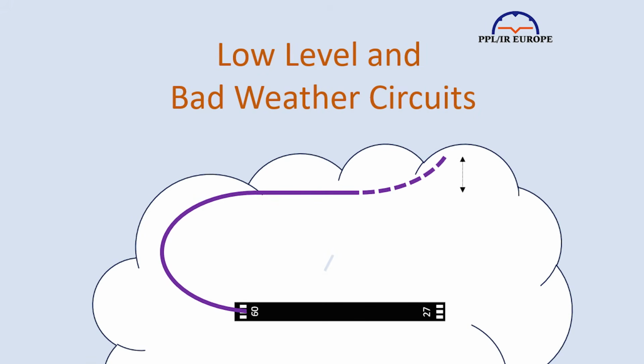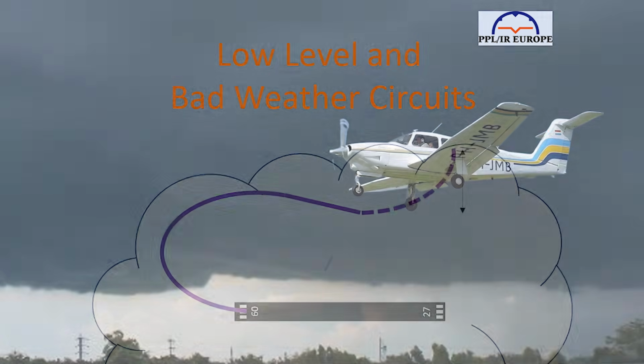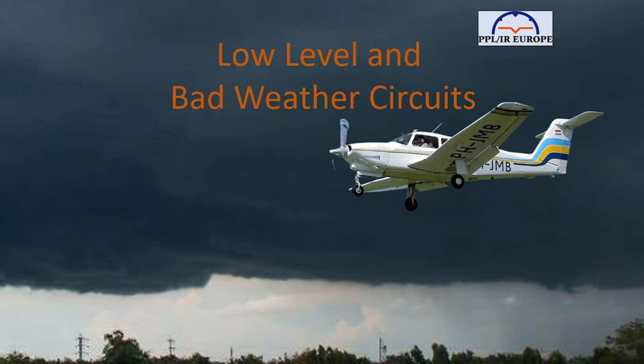From a 45-degree angle, that's manageable, about 250 metres closer in, but from a 90-degree cut, using a rate 1 turn, which is the maximum I'd suggest given your low height and the dangers of disorientation and spinning, it's close to half a mile. I would suggest being fully configured for landing before you join downwind, at least as far as is sensible and permitted in your aircraft type. This saves configuration changes and the loss of stability and disorientation they can cause in poor visibility and low level.